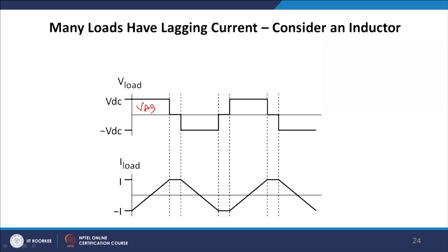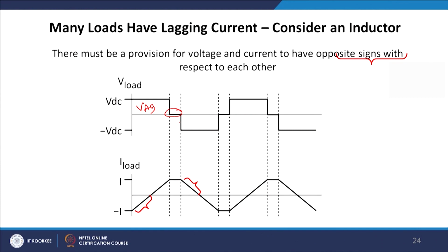Thereafter, once you apply the negative voltage, then the current will again come into place and drop, and we will have a 0 cross. Thereafter, the same will happen here in the plateau region. So, what happens, by changing this value you can increase or decrease the value of your RMS voltage. This is the operation of the simple square wave inverter.